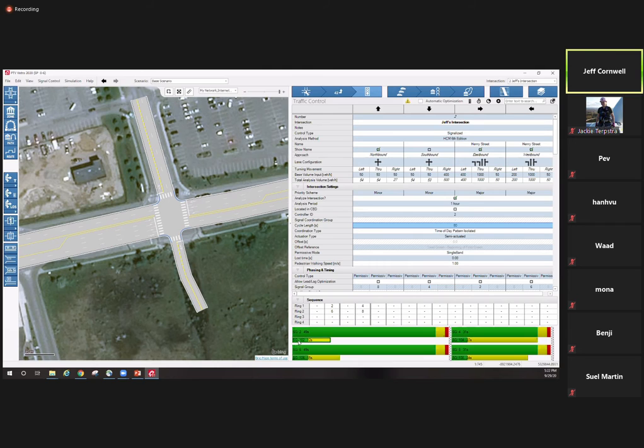And then down here, this is showing the ped time, I believe. The walk in green, the flash don't walk in yellow. And then here you'll have the sequence. You'll see here we've got no left turn phasing, so ring 1's using phases 2 and 4, ring 2's using 6 and 8. That will match the ring and barrier diagram that I've shown you in the PowerPoint, if you want to go back and look at that later.